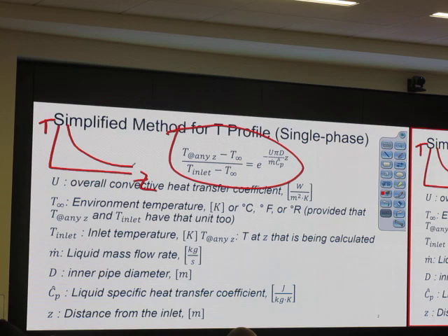If I use the maximum possible U value, I get the lowest possible temperature estimation. The actual temperature cannot be lower than that. So this is the conservative approximation. At most, we have just that much heat loss.